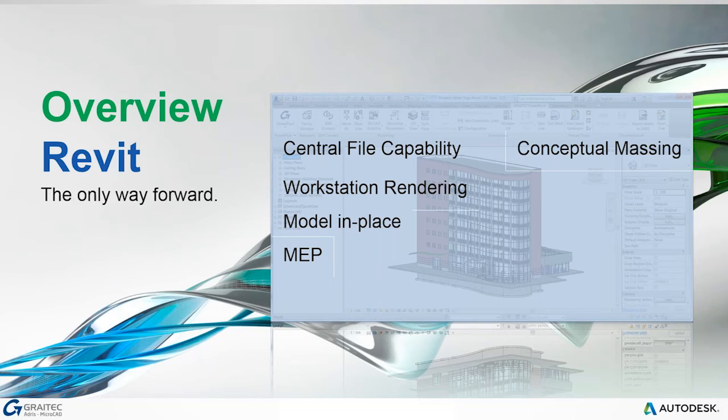Historically, this is the kind of work that would have been done with programs like SketchUp. Now, one of the advantages of doing it inside of Revit with the Revit tools is that Revit knows what it is. Even though it's just a mass, a 3D solid effectively, it happens to know what its overall mass is and what its volume is. And in fact, you can easily add levels to it for where the floors are going to be. And even at that stage, you can start receiving information out of that mass model about what the overall area is. What is the actual floor area of that entire building with the levels that I've put in, but it's still just a mass model.